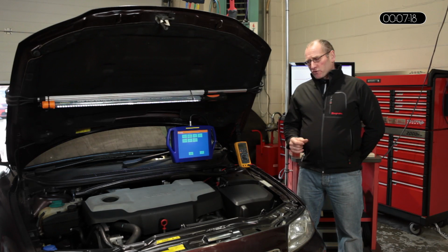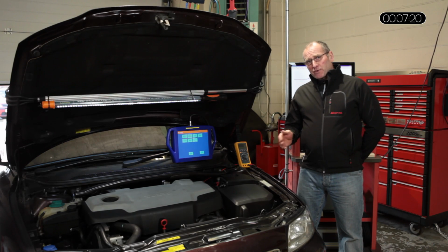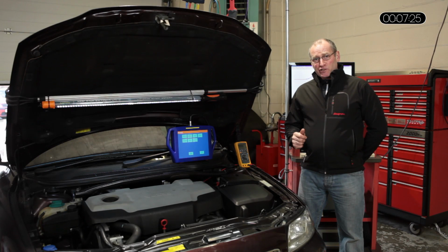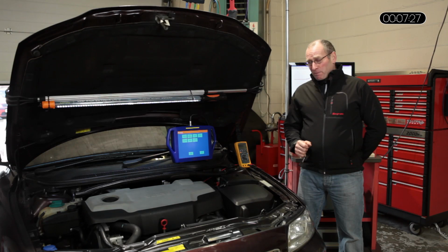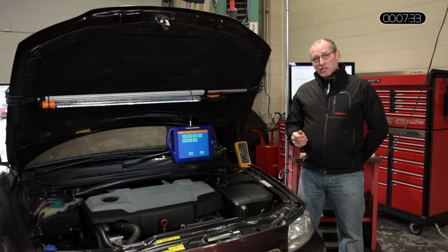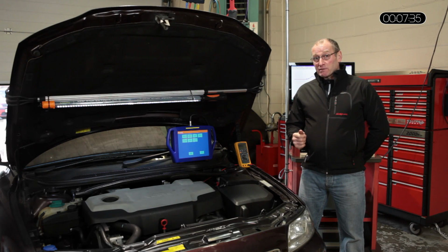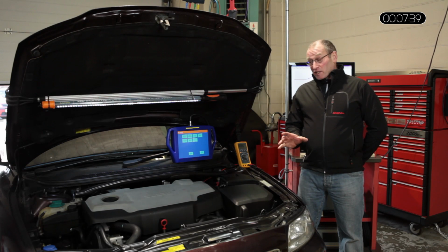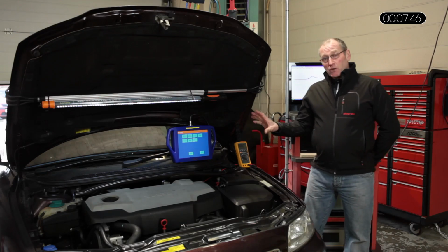Full power's restored, flexible right from the bottom end, right through the speed load range, with absolutely no discharge from the exhaust at all. So it really is a very effective repair. Total cost about £800, which in relative terms is very good value for money when you consider that a new DPF alone was £800. So it's a very effective repair, and from the point of view of the independent industry, a very profitable repair in terms of time against income generated. But let me start the engine, go through some data.